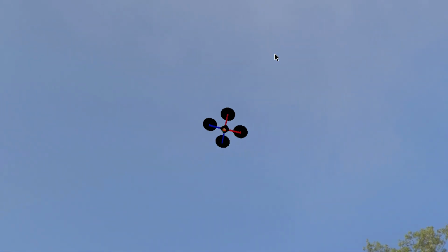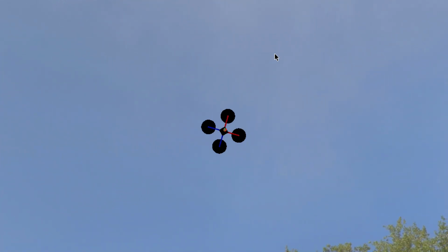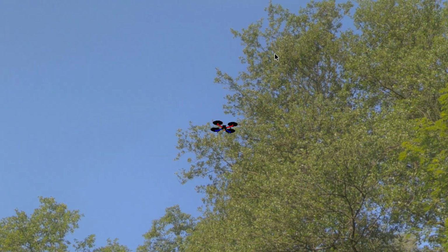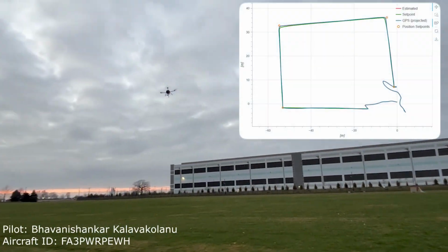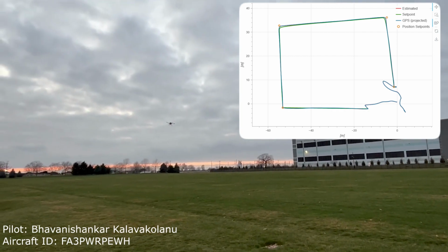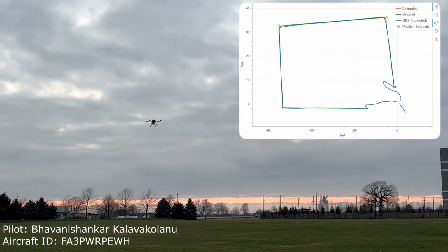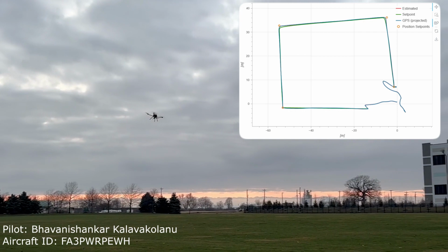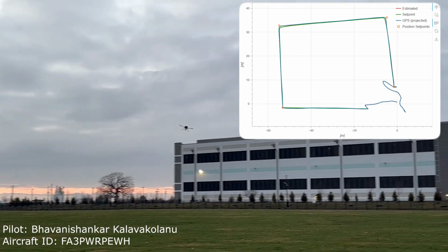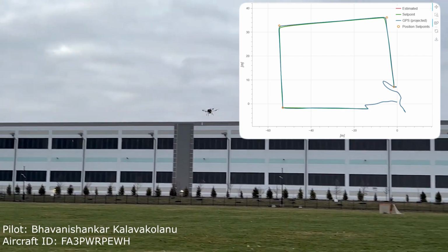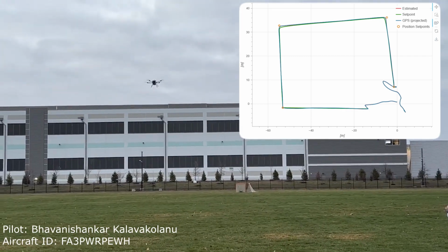Once all the vision target locations are identified, their coordinates are stored in a map, where the key is a unique identifier representing the combination of vision targets, and the value is a list of coordinates corresponding to those vision targets. The team conducted over 45 autonomous flight tests. Each test consisted of a manual takeoff and landing. Through all the tests, the team has attempted over 250 waypoints and successfully hit all 250, leading to an average miss error of 0%.